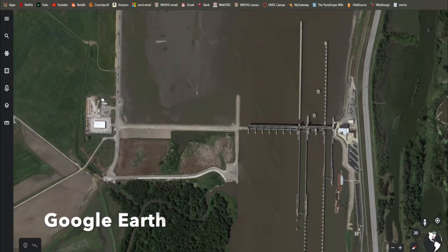We picked these 4 places since they were all non-powered and within the Missouri-Illinois area, and they looked like they best fit our project. Using our quantified needs equations, we were able to score these locations and finally pick the Melvin Price location. The Melvin Price Lock and Dam was chosen mostly for its high overall power potential, good volumetric flow, better fish pathways through this lock area, better expected LCOE, and good accessibility from this side.